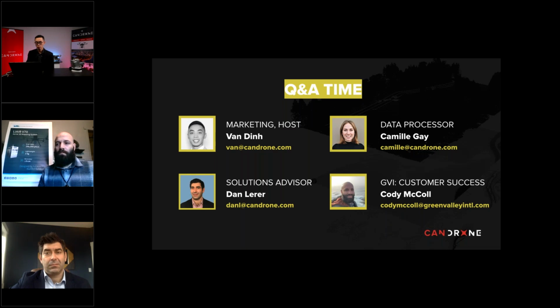Cody, do you want to add anything to that? Yeah, you were right on the button. LiGeo reference is technically considered a pre-processing software proprietary to GreenValley products, where LiDAR 360 is post-processing. It gives you more functions for analysis, and you can utilize data collected by other devices. With LiGeo reference, it does allow you to do everything that DJI Terra does automatically, but it gives you the ability to do it manually, with a couple of extra features. You can colorize your point cloud if you get a device from GVI that has a camera built into it. But yes, they are very similar.